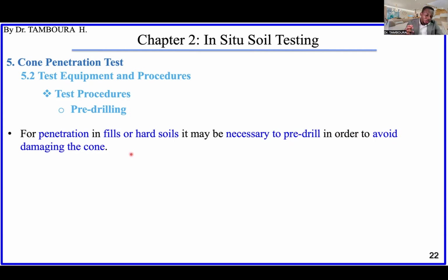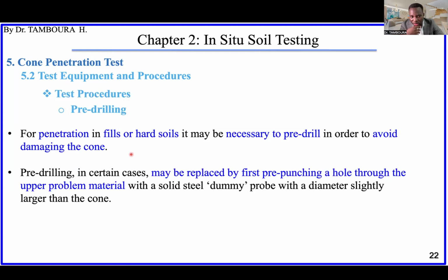You will not just start using the cone. Sometimes the surface layer is very hard, so remove that layer before starting to use the cone. Otherwise, you will damage the cone.